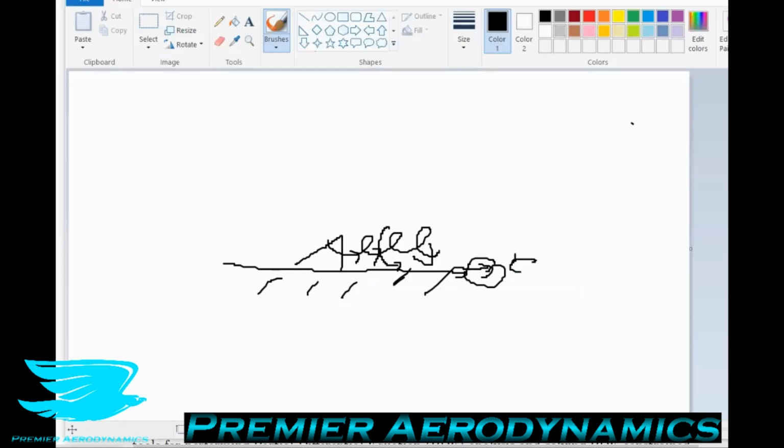So vortex generators, they're a big family, and you can get different sizes and different heights and different shapes. Generally speaking, they can be divided into two different sizes. One is the regular vortex generator, which means that they are about the same height as the boundary layer, more or less, plus or minus 20%, let's say. Then you have micro vortex generators, and they are usually about 30% to 50% of the boundary layer height or less. And the difference is that micro vortex generators have been found to be pretty much just as effective as regular vortex generators, except they don't have the drag penalty.